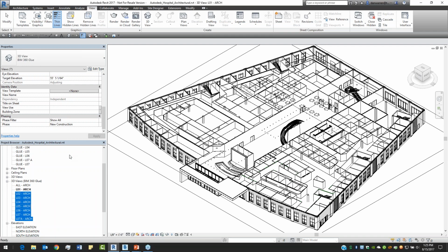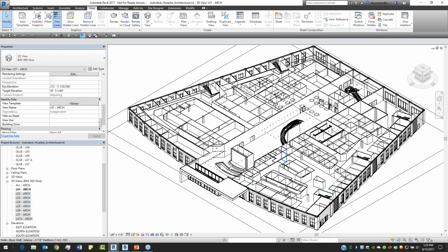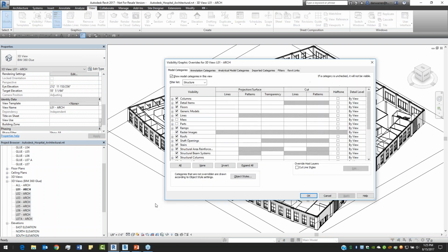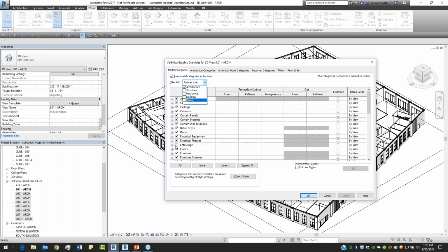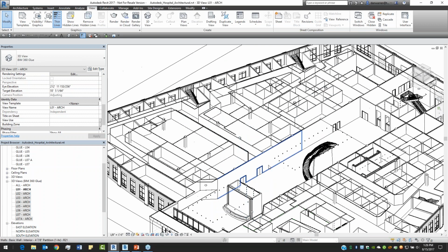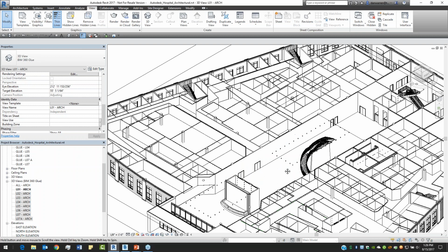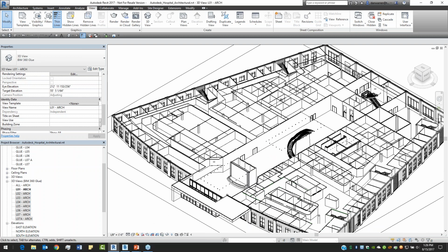So just a quick refresh, we're going to create a floor plan, use the view range, use the view cube to orient our 3D view to the floor plan, and then we're going to use a view template to make sure that we're hiding things per our standard, right? So like in this example, I probably wouldn't need the furniture turned on, so I could go into my visibility graphics, come down to furniture, and we turn on architectural, turn off furniture. You see all the furniture is hidden because we don't really need to worry about furniture during coordination. And now this view is ready to push up.